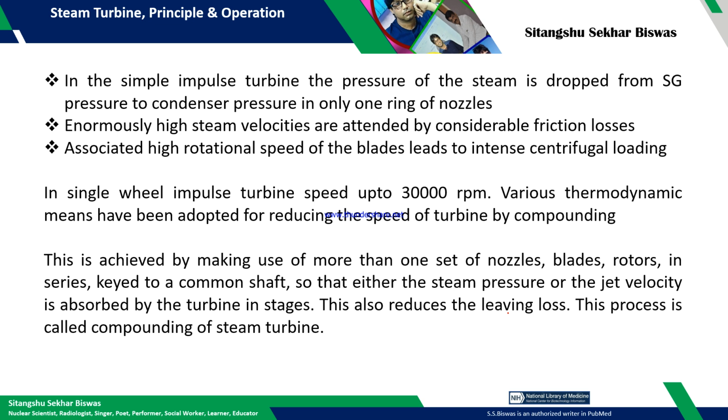And this 50% contribution is possible, and mathematically we have established that the absolute steam velocity at the inlet should be the relative velocity of the steam at the outlet, and vice versa, and the corresponding angles are also to be identical.